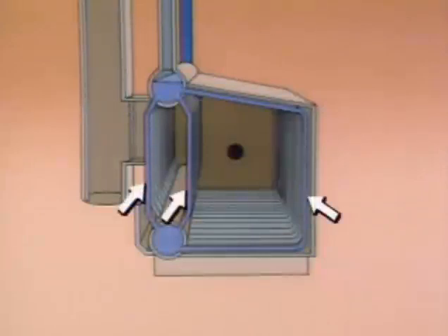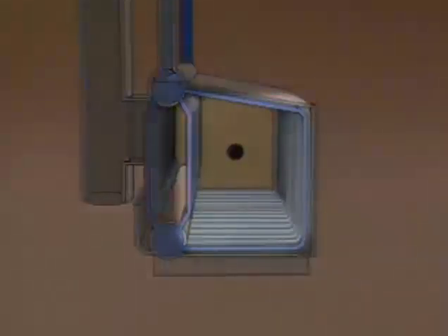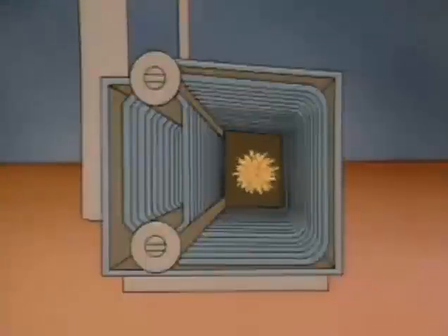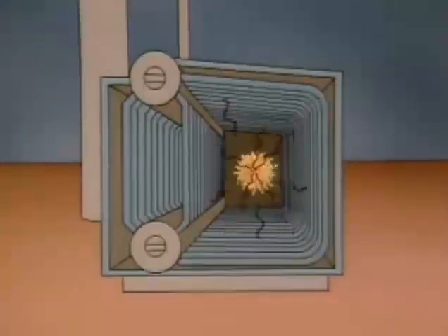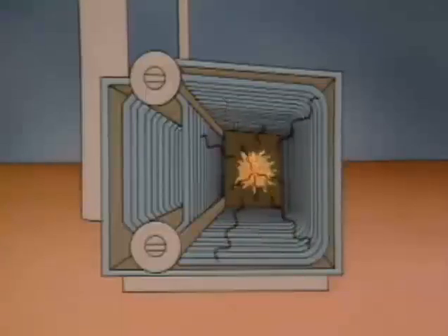The boiler has a series of tubes and two drums which distribute water to the tubes. The tubes form a wall around the combustion area. This is the area where heat is generated. When fuel burns in a boiler, radiant energy in the form of electromagnetic waves is produced. These waves travel through the combustion area. The waves in a direct line of sight with the tubes make contact with the outer tube surfaces, and the tubes absorb heat. This is radiant heat transfer.